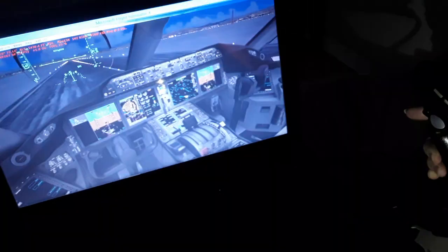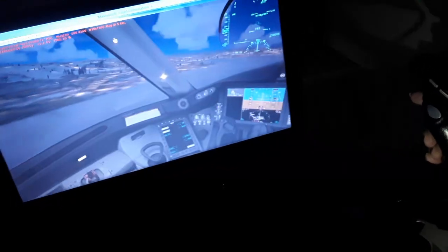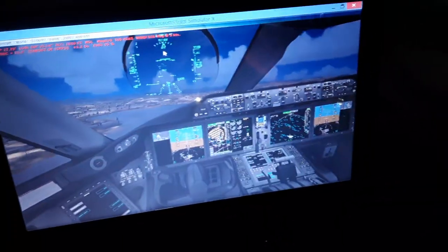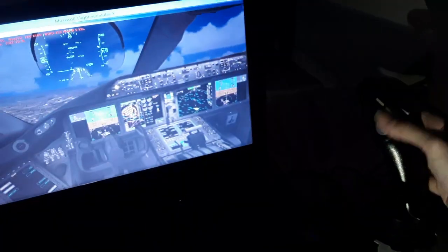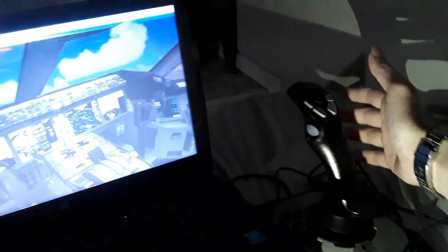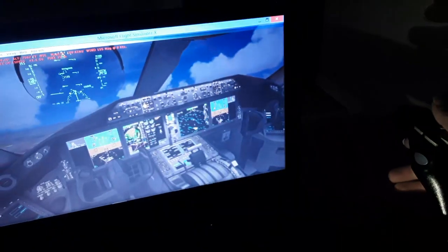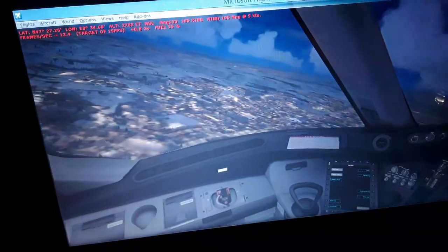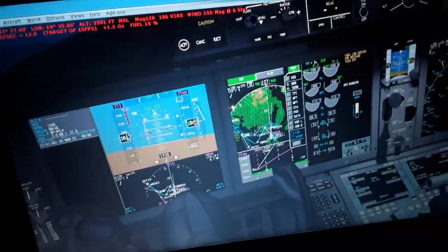So we pitch the aircraft slightly 9 degrees for rotation, take off rotation like this. So we have positive rate of climb like this. Let it gear up. We can leave the hands off from the side stick, no problem, as you can see as we climb, because it's well trimmed and it has maximum takeoff power thrust set. So you can see we're climbing, hands off, no problem. Only an aircraft can do that, flying hands off.